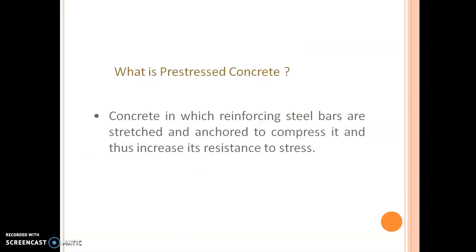So, what are prestressed concrete structures? They are very similar to reinforced concrete structures. In reinforced concrete structures, you have a concrete section and you reinforce it with deformed bars. Here also, in a prestressed concrete section, you have a concrete section and you reinforce it, not with deformed bars but with strands. Here the reinforcement is called strands or tendons. The overall section remains similar, but the main difference is that in prestressed concrete structures, the reinforcement element, the strands or tendons, will be stressed initially.